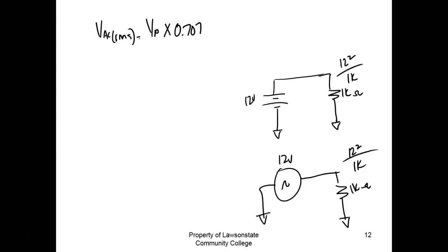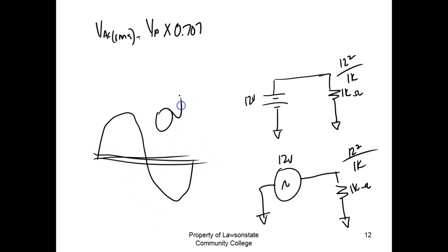And it can't be an average because what's the average of this? What would be the average voltage? The average voltage would be 0. We proved that. I can take this meter right here, I can put it on DC, and I can put it across that transformer, it's going to measure 0. Because what your DC does is it gives you the average, right? It gives you the DC average of a cycle. What's the DC average of a cycle? 0. So they had to come up with a method where we can do away with the minuses, right?